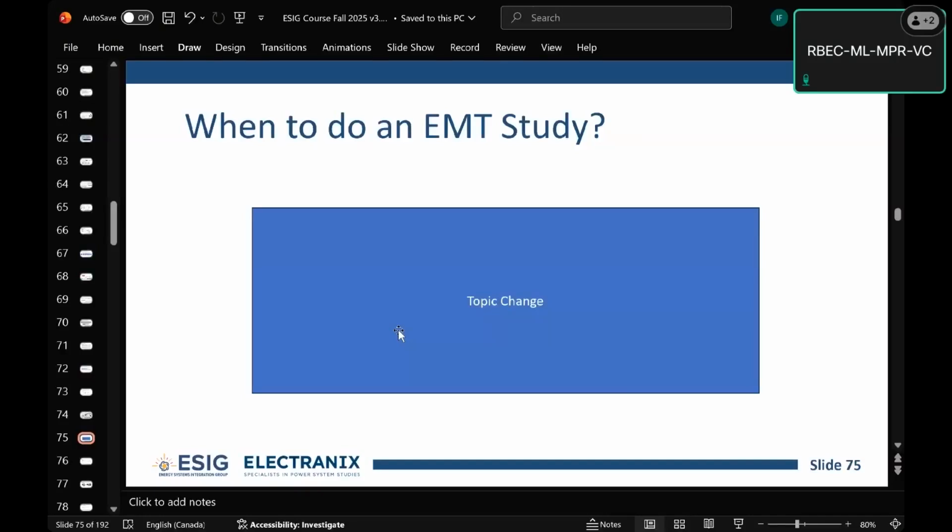All right, so before we finally leave the SCR topic, I want to just emphasize that SCR-based metrics, at the end of the day, you want to use them for screening in some way, not for making final decisions, unless it's a very blatant thing. Like if you have an SCR of 0.7 and somebody wants to connect and it's a very simple case, it's a red flag that's strong enough that you can say, no, pass on that one, right?